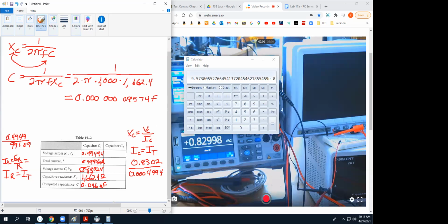All right, so this brings us on to procedure: this value should agree with the value marked on the capacitor and measured in step 1 within experimental tolerances. I'm supposed to get 0.1 microfarads and I got 0.096 microfarads. Pretty darn close.